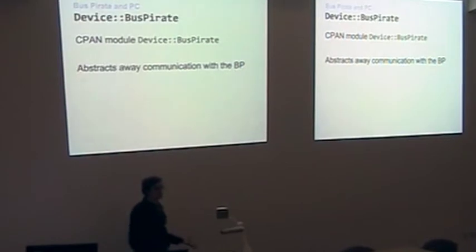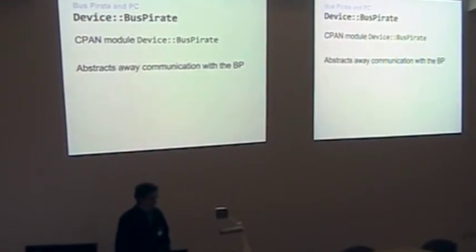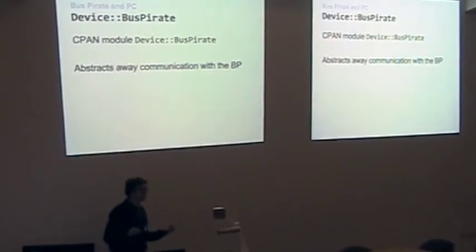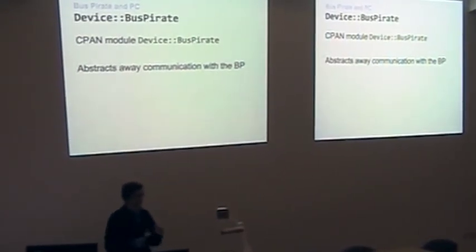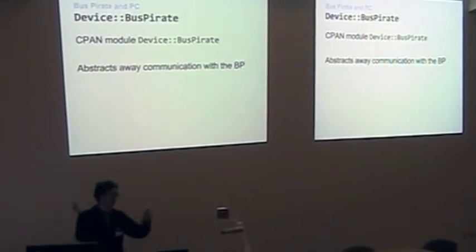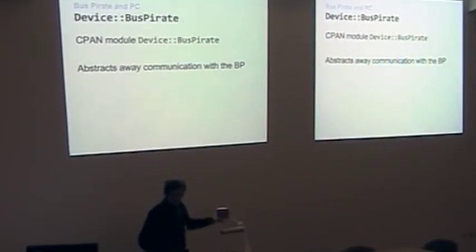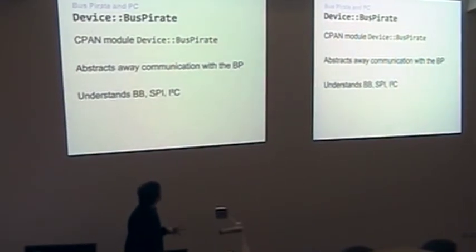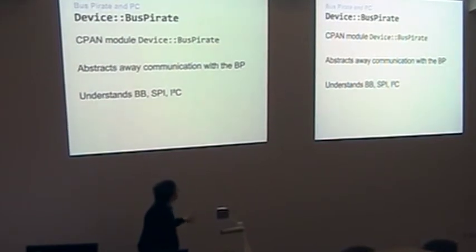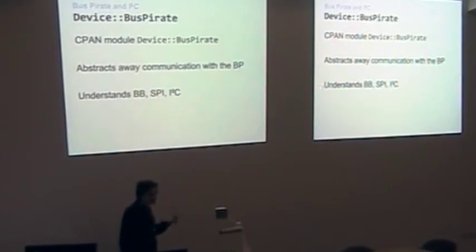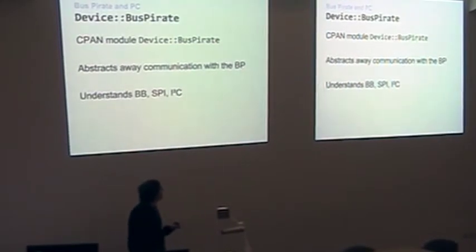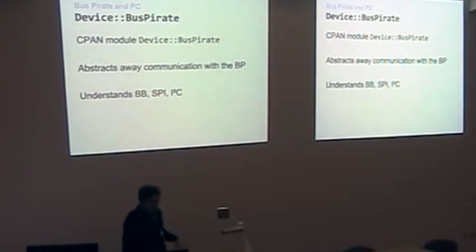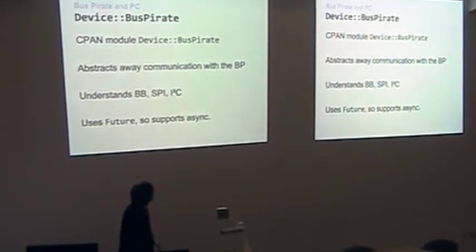That wraps away all of the communication with the Bus Pirate. So rather than all of their example scripts, where in every single script they open the serial port, they set the serial lines, and then they send some bytes, and they read some bytes, and they have to know that these bytes in this particular order mean this thing, blah, blah, blah. Throw that all away. Have this abstracted interface, because that's what we like, right? So the module currently understands bit bang and GPIO, understands SPI, recently understands I2C because I added that, which I had to do. It doesn't understand the other bits yet, but I'll maybe add them at some point if I have need for them.